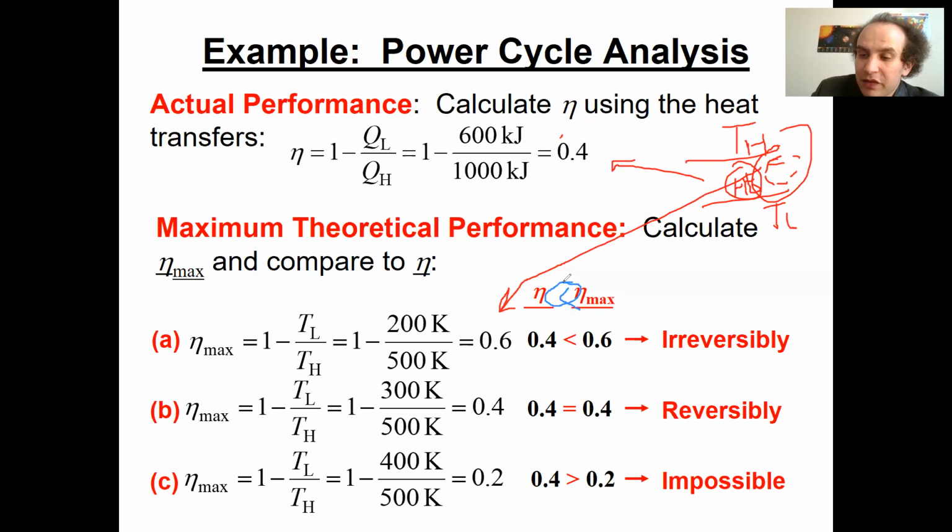So if your maximal efficiency is 60% and your efficiency is 55, you say it's reversible. And if your efficiency is 59.5, it's reversible. And if your efficiency is 5%, it's irreversible. And if your efficiency is 59.999, it's still possible and irreversible. You don't distinguish these cases. Key point, it should be less. How less, you don't know.